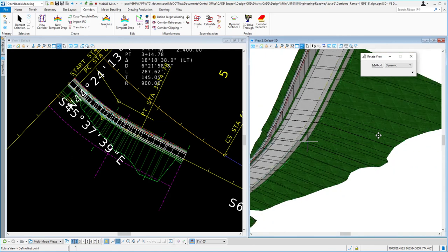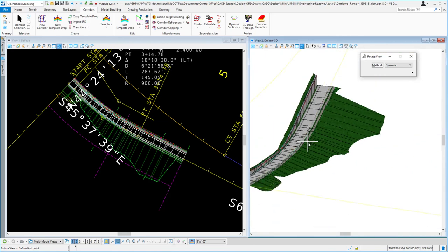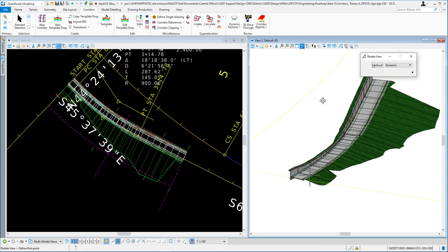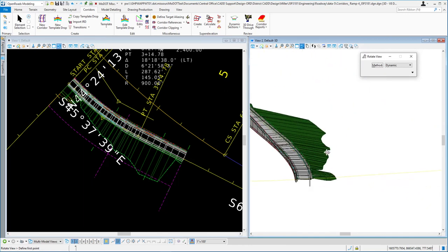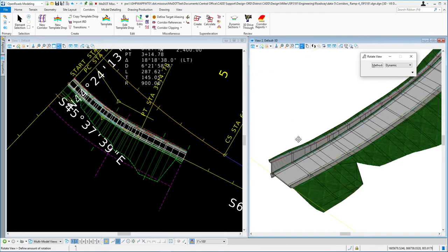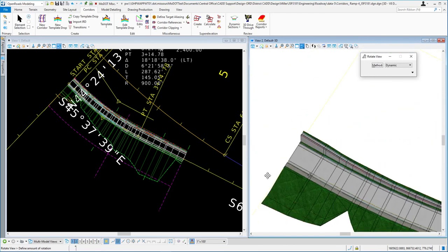Yeah, pretty cool stuff. But that is the biggest tip I can give you with this rotate view. Take that crosshair, and wherever you want to see it, you move to it. Now you can also use your middle mouse button, I believe, to left click and hold down and move, and it will pan. But once you've got that set, then it's just left click and rotate, and then you can zoom in and out of that point. So that's your pivot point. That crosshair is very, very important.